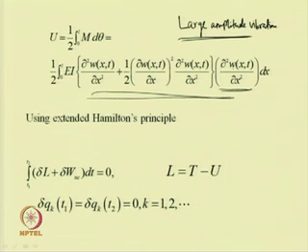So in this case, one can have U equal to half E I (del square w by del x square) whole squared, or one can take del square w by del x square common. If one takes it common, then it becomes 1 plus half (del w by del x) whole squared, into del square w by del x square. So one additional term one can get in this case, that is half (del w by del x) whole squared. This term will lead to the nonlinear terms if one derives the equation of motion.